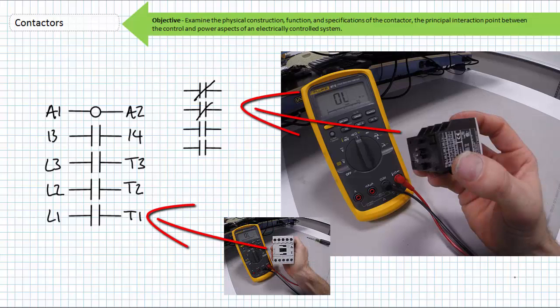If the system warrants its inclusion, something known as an auxiliary contact block can be slid in position on top of the main contactor, actuated by the same plunger. Notice the slots in the face of the contactor and the accessible portion of the plunger match the back of the auxiliary contact block. As the plunger in the main contactor is pulled into the coil, a clip pulls the plunger in the auxiliary contact block as well, and those switches associated with the block transition to their opposite activated state.